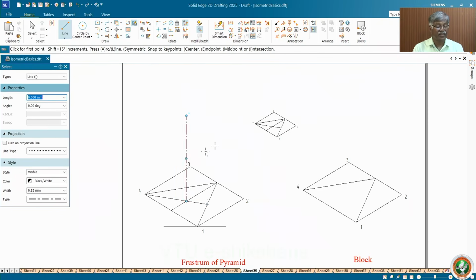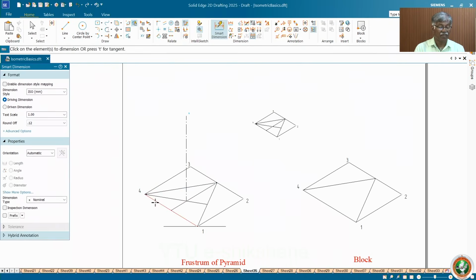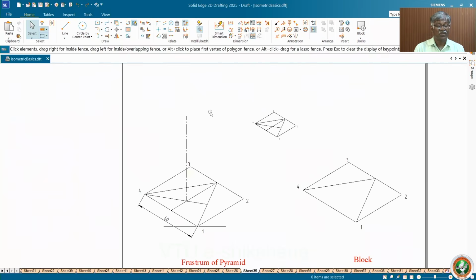Yeah, you got the axis reference from the center OB. Now relocate this figure which you already scaled. This is 25. Okay, this is 60. Now let me see, this is 25. Yes, this is 25, you see, 25. So you have to relocate this such that the center of this coincides with the top of the axis.